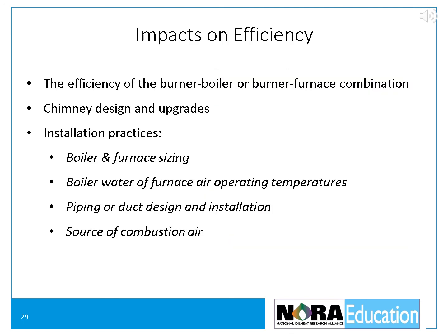Impacts on efficiency. The actual efficiency of the oil system is affected by the following factors: the efficiency of the burner boiler or burner furnace, the chimney design and upgrades, installation practices including boiler or furnace sizing, boiler water or furnace air operating temperatures, piping or ducting design, sealing and insulation, and the source of combustion air.